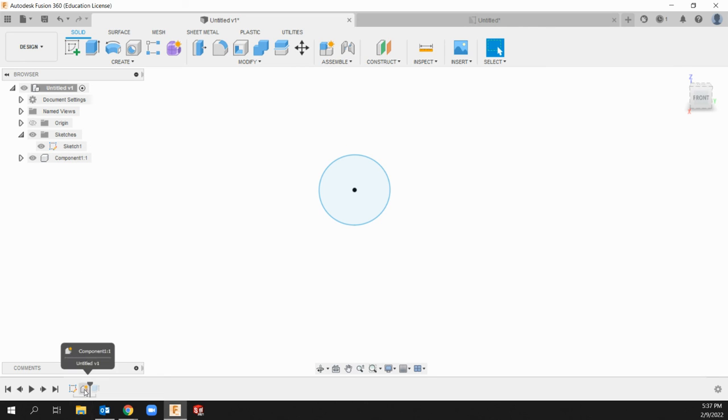see now we have active as component, and I will see this component 1, and if we highlight and click once, we can change the name and assign a name to it. So now we call it circle. And we'll see we have origin. Now this will apply for any component, but still we have no solid, because once we had our sketch, we created a new component into a solid. Once we slide that ahead, that timeline, we now see our solid.